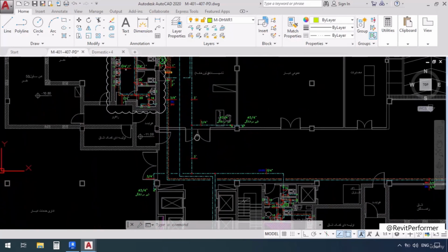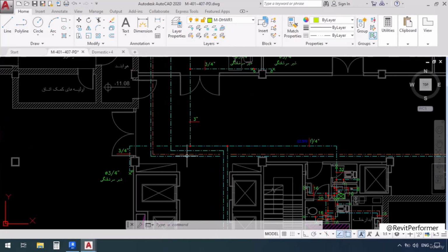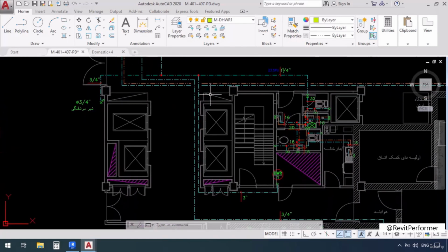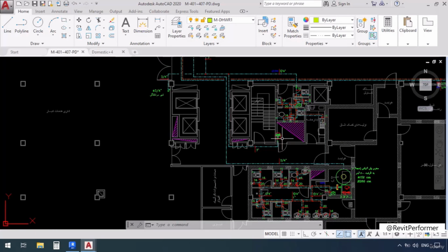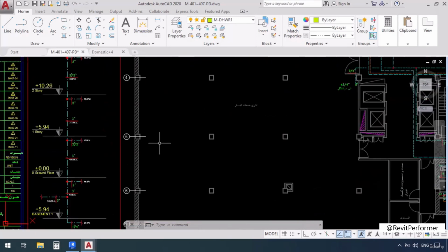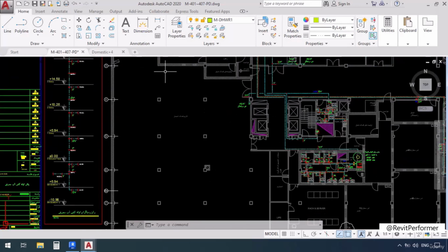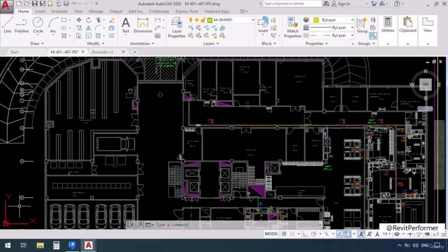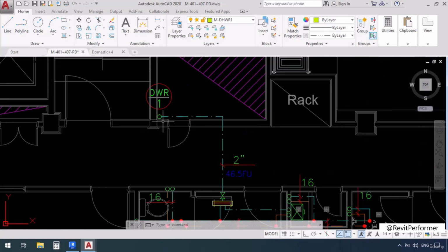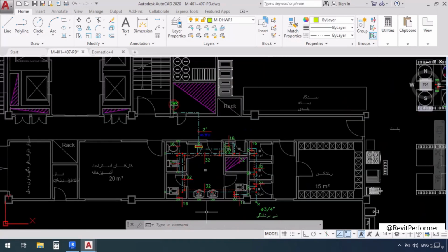If we take a look at the branch on the right, we can see it coming down this way, and then finally it leads to this riser to the next level, domestic water riser. So now let's go to the grid to see where it's located, grid 5, and now let's go to the next or the upper floor. Let's go to grid 5 here. Here's this riser which feeds these lavatories.